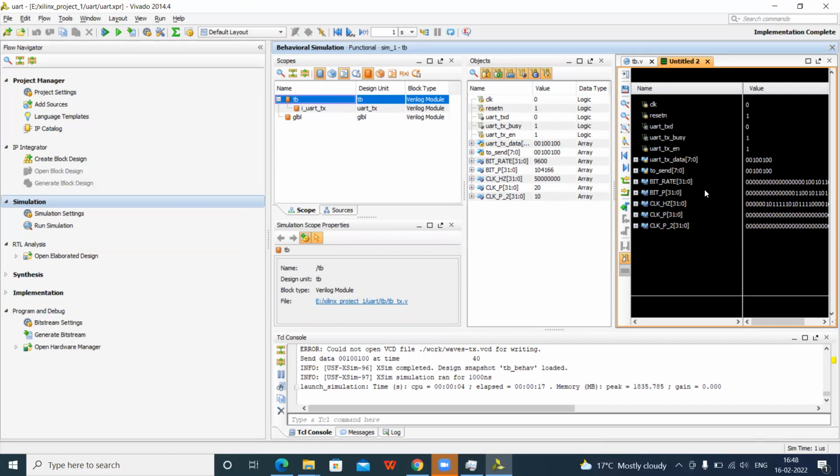On this simulation, you can learn a little bit about UART. So what you have done: you can say that you are TX, so you have TX bytes and TX data is transmitting here. Then you can open the reports, like report synthesis, whichever points I had shown you. You have to take a screenshot of this, and I said you have to see the device view. Also, you need to see the schematic here. All these things you can show that after synthesis we got all these things.